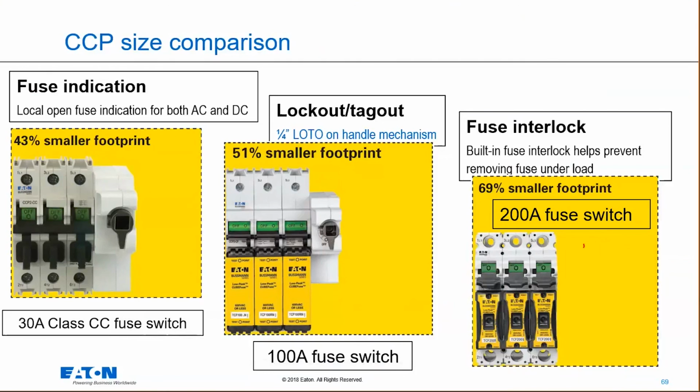On the 200 amps, they're a little more modular, meaning we can add through the door disconnects and we can add side disconnects. And on all three of these cases, you could just have them inside of your panel. So maybe if you have multiple drives in your panel or some large contactors, and maybe at some point you want to isolate them, you can have a disconnect inside. So that's a toggle disconnect that we can utilize, and that is all available now.